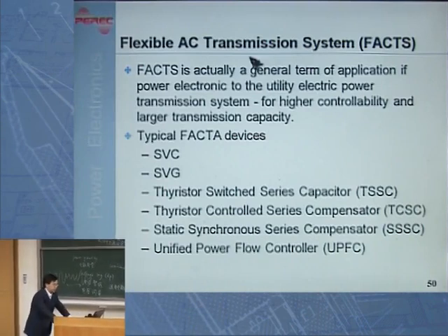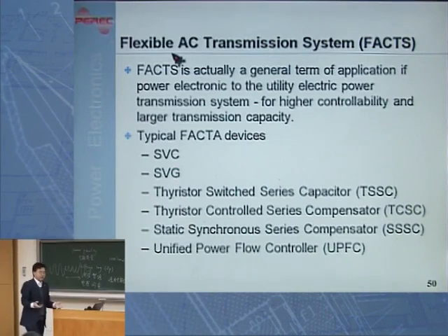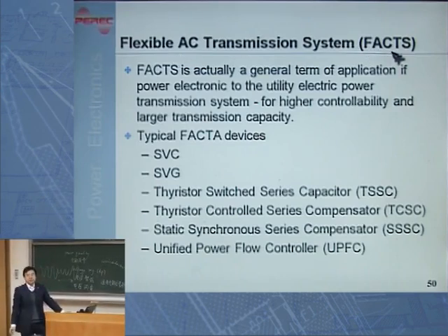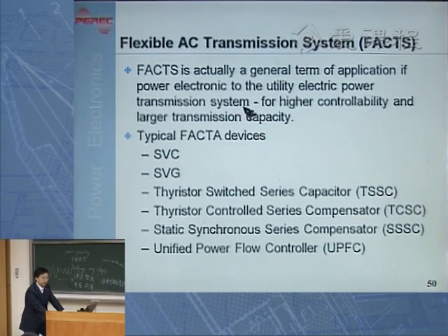If this is applied to a transmission system, there is a special name, which is called flexible AC transmission system, or in acronym, FACTS. FACTS is actually a general term for applications of power electronics to the utility electric power transmission system in order to achieve higher controllability and larger transmission capacity.